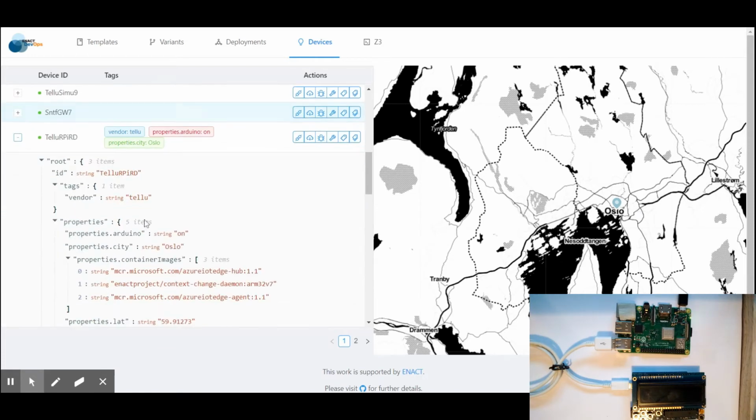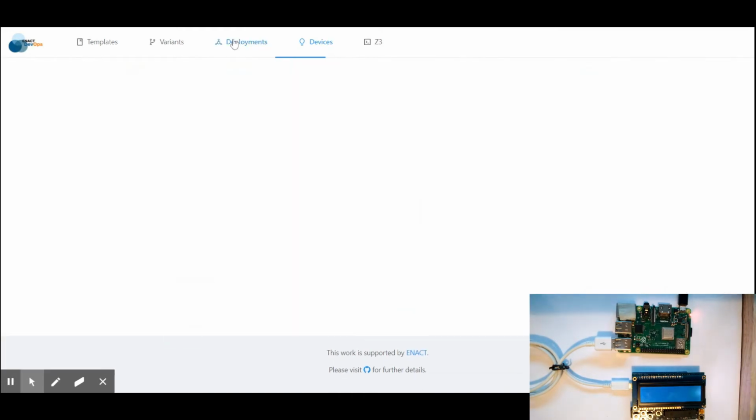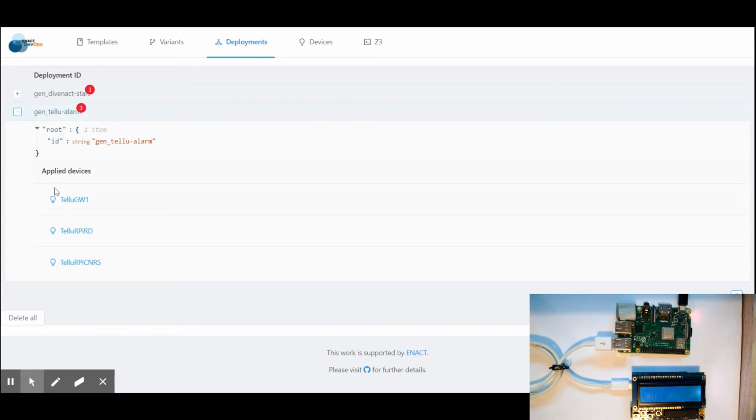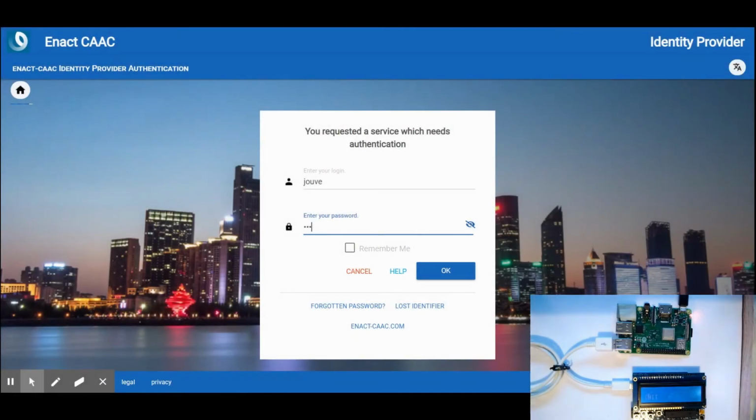This means that the Arduino board has been flashed with the corresponding alarm button firmware, while the Raspberry Pi is now running an application to communicate with the Arduino over the serial port. This so-called last mile deployment bundle is implemented using Genesis, to which we pass the corresponding model with an Arduino sketch. Now that we have both Arduino and Raspberry Pi updated with corresponding software, we can start using the new